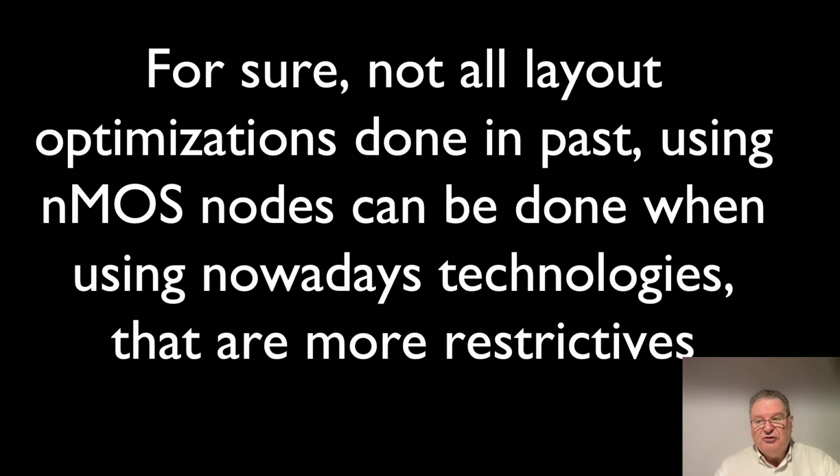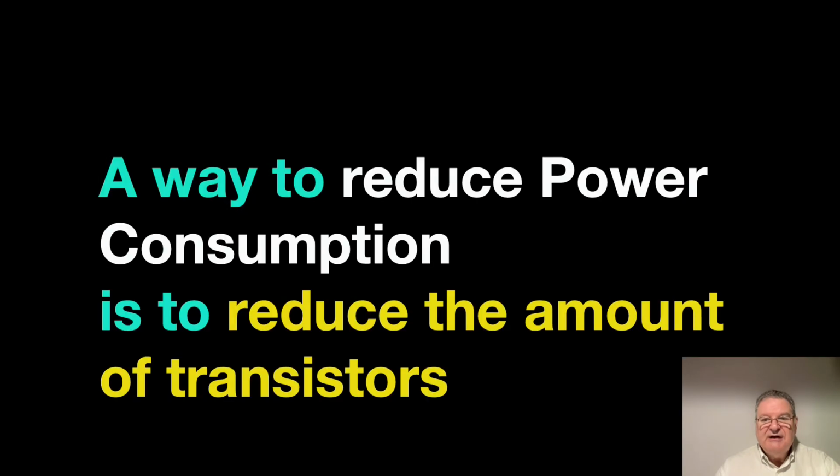And we also don't know what the technology will be in the future. So it will be interesting if you have a new technology where you can have just one transistor from the output to VDD, like an old NMOS, and then we will be able to do much more complex gates with a larger set of inputs.